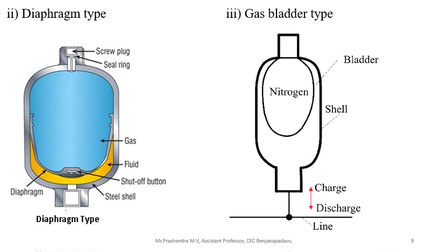See, here there is a chamber provided. This is a chamber provided to store the pressurized liquid, and here is the gas chamber. So when pressurized liquid comes and fills the space and pushes this nitrogen gas chamber, the bladder gets compressed, and the potential energy of the liquid is stored inside the accumulator chamber.